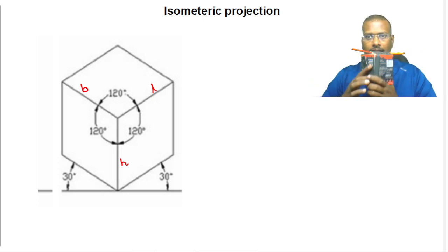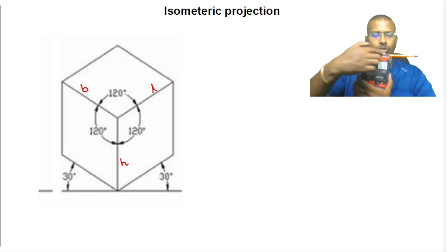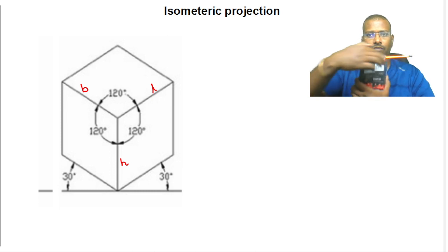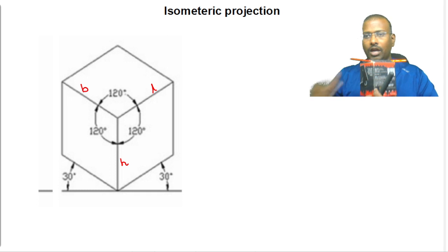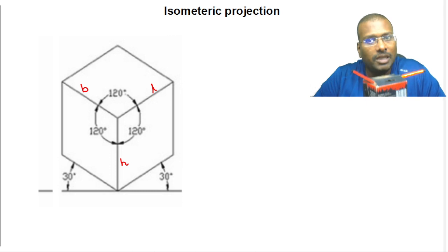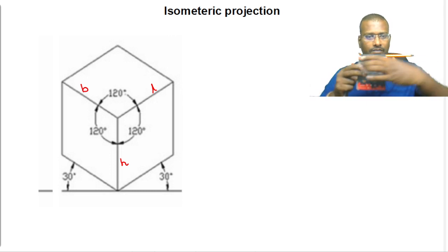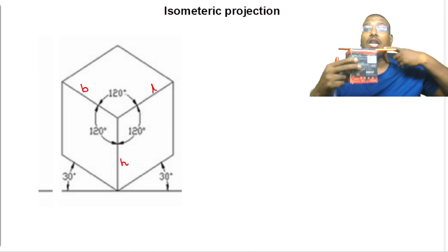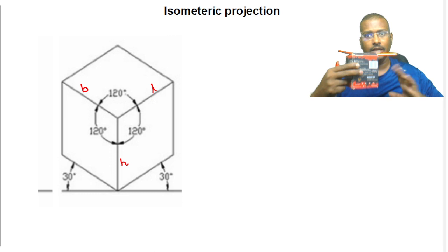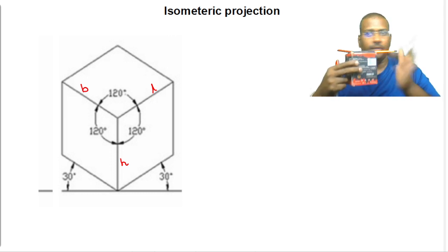Once it is tilted like this, here you are going to get the true length of the object. Once you tilt like this, you are going to get it reduced. Breadth is also the same. Once you rotate like this, here we are going to get the length, but it is going to be compressed. How much is it compressed, sir? Once this line is inclined to HP, the front view comes parallel to the XY line, but reduced. Is it clear? Now length is going to be reduced.